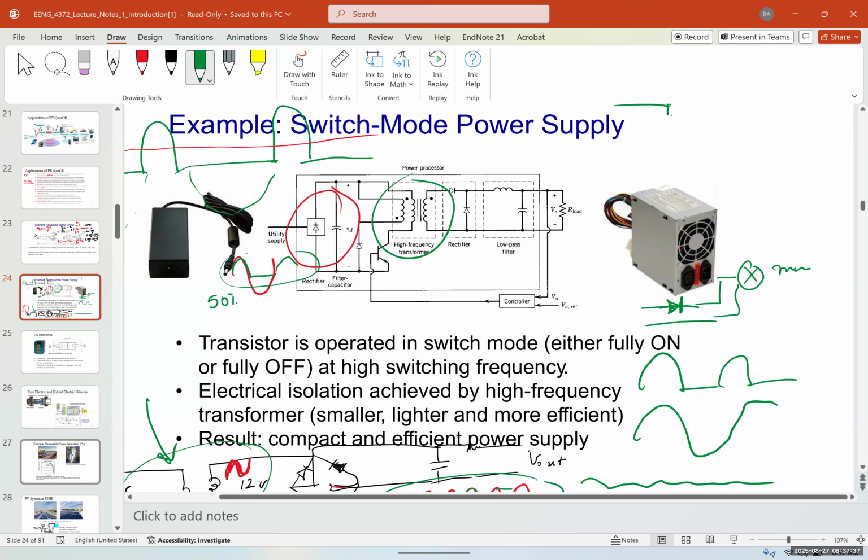So without the diode, the whole power goes through the heater. You would have maximum heat. But when you put it on low, you have half of it. Some of them also have a coil that cuts off this heater. Some of them have low, medium, high. That's different. But most of them just have low and high, the cheaper ones. When you put it on high, the switch is connected to the one here, and when you put it on low, it's connected to here. So high and low. Okay, so with these two switches, you can switch between the diode or without the diode.